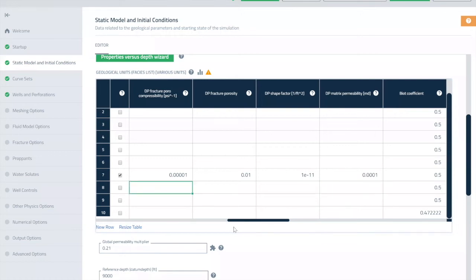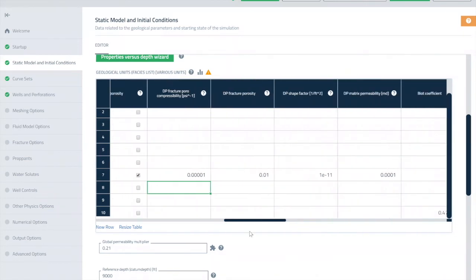That's the main point. When you use dual porosity, the region around the hydraulic fractures that has enhanced pressure increases in size. It gets broader. And so then you're going to defeat that mesh dependence, because you're not just leaking off into one element anymore, but you're leaking off into a lot of elements. Now, there's still some potential for mesh dependence. Certainly, if you think SRVs are 10 feet wide, then you need to make sure your elements are at least 10 feet wide, right? So you may want to refine a mesh if that was the approach that you were using, in addition to using dual porosity for the leak off.